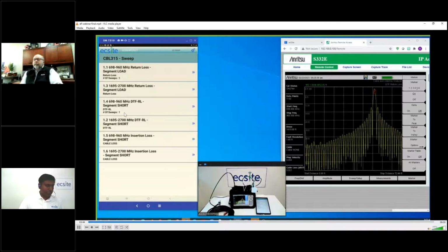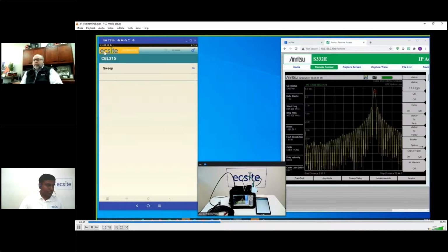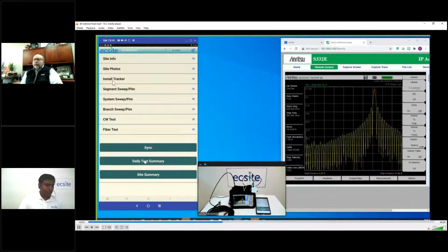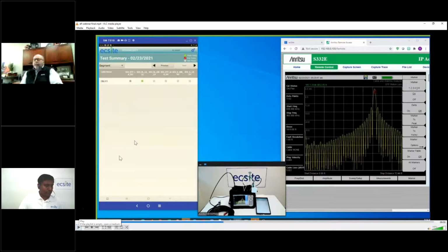Right, so now I have a second test result, and if I go up, it still says black because all the tests are not complete. And now I want to see what I have done today, right? As a technician, I touched cable 315, and I have done a DTF to a short and a return loss to a load. The DTF is usually not a pass-fail test, and the return loss is a pass test. So you see what they have done. That is what the technician has done for that day.